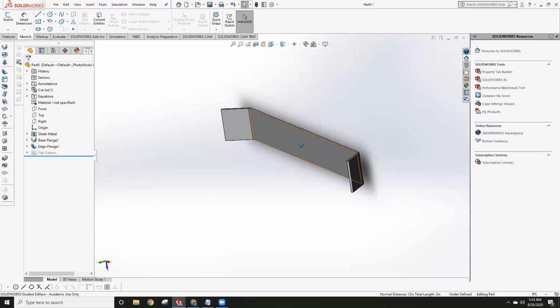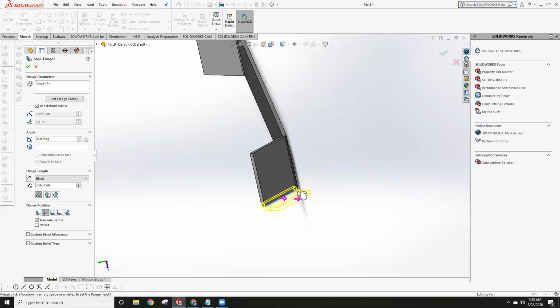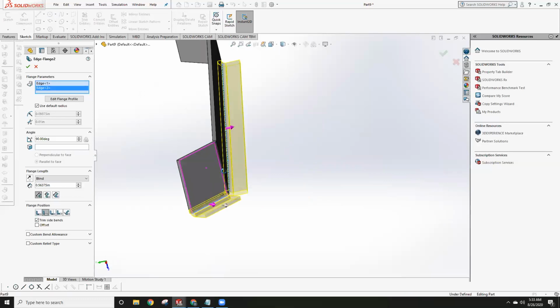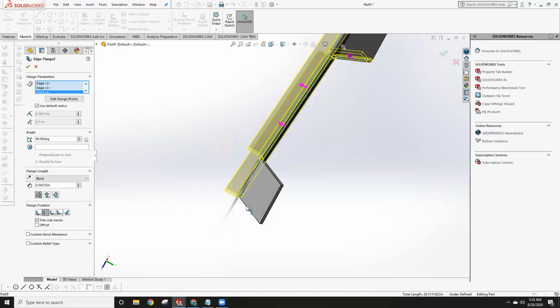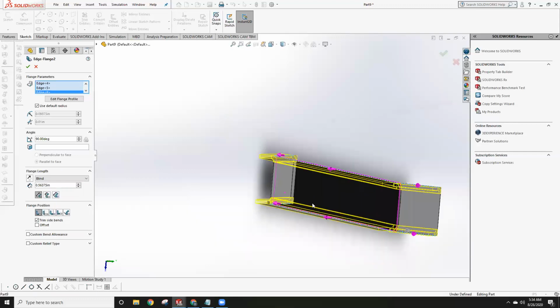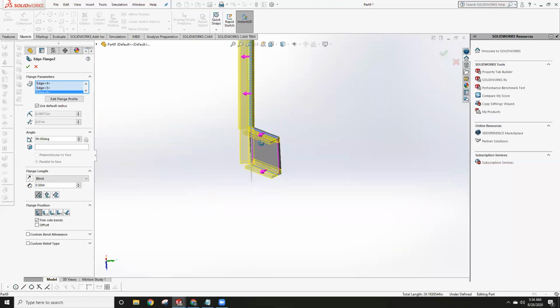Cool, looks great. Then this is the important part for this piece. Whenever we make our mounting flange, which we're going to put right here, we're going to do material inside, because this piece and the front piece are going to be wedged between 2 panels. And so I'm just going to keep material inside so I know the exact distance between the 2 panels. That will just make everything a lot easier. So we're going to make this 0.5 again. And I did this on the outside. So all these are going out.